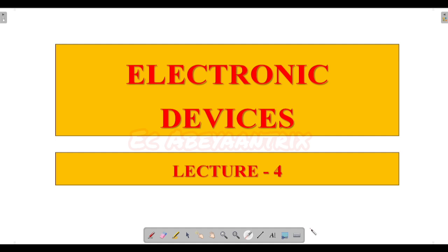Okay, so what are the different applications of the PN junction diode, and how the VI characteristics can be plotted for a PN junction diode, whether it is a linear or non-linear device, and so on. We are going to discuss a lot. Okay, and also we are going to mainly discuss the diode current formula, that is the Shockley diode equation, and the various terms involved.